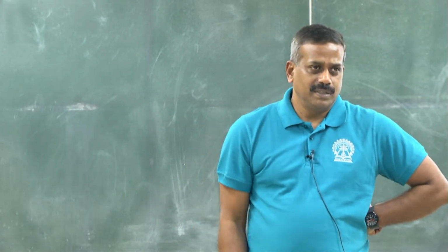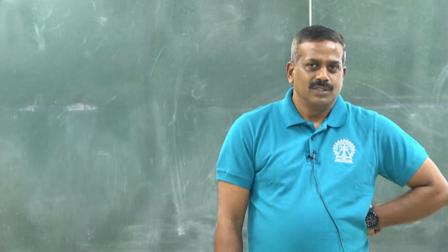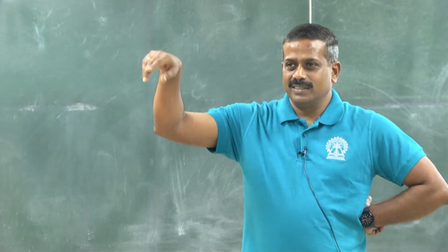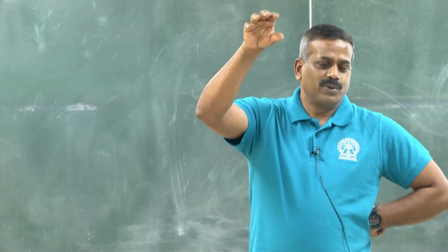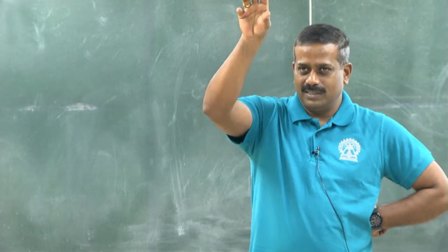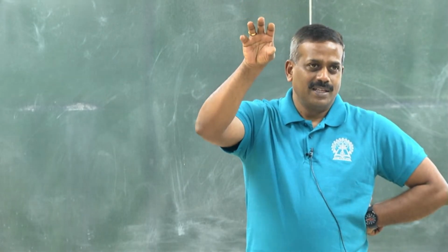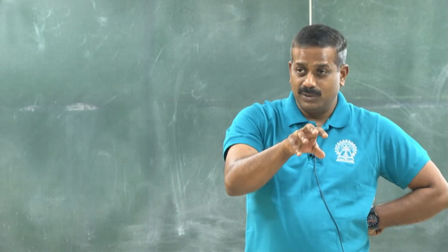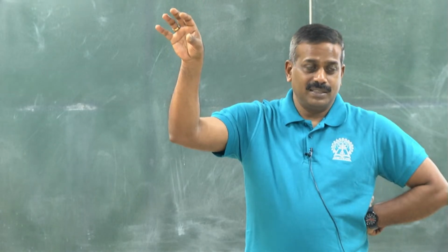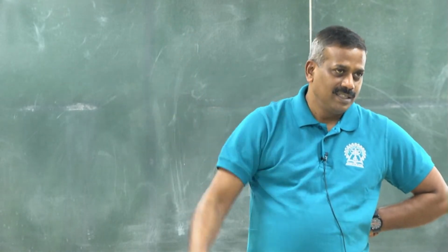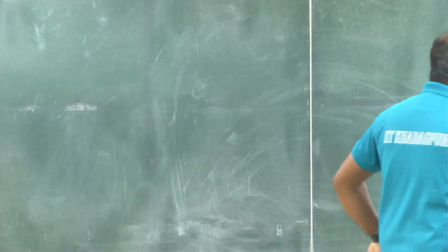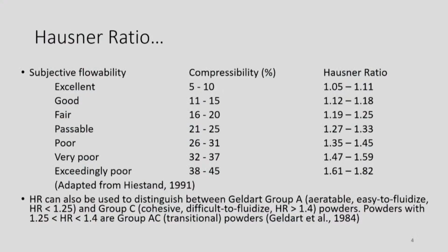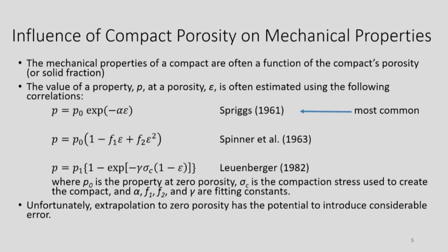It's a relationship between particle size and density. You might have seen two or three lines inside. One section within the graph shows good fluidization behavior of powders if their relationship is in that area. If it's a very fine powder, it's very difficult to aerate. If it's large particles, then it will also be very difficult to fluidize. I gave the example of popcorn, popping: it will sprout, then fluidize. So the Hausner ratio can indicate the fluidization behavior of these powders too.